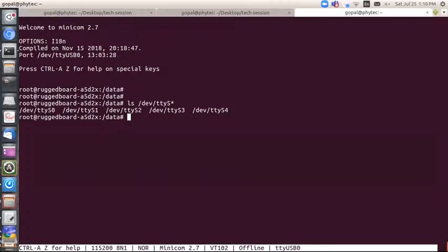There is one more tool called microcom, and by using microcom we can straight away test how this port is activated, how this port loops back. Of course, once we short TX and RX, whatever data we give will be reflected back to user space. Through that loopback we can easily test the UART without writing any application programming. Of course, we'll show that also.